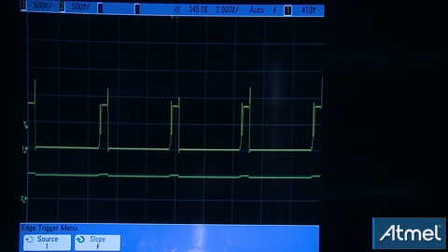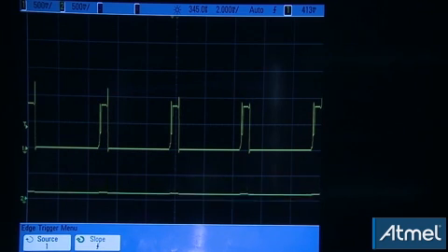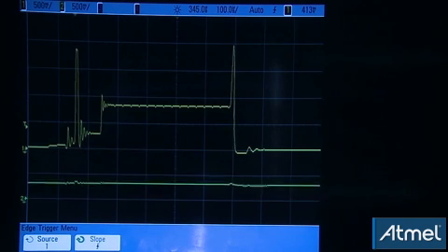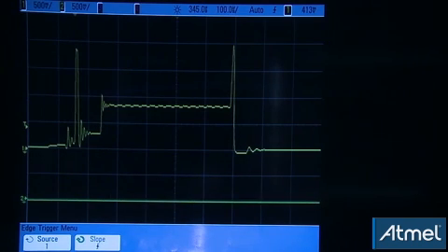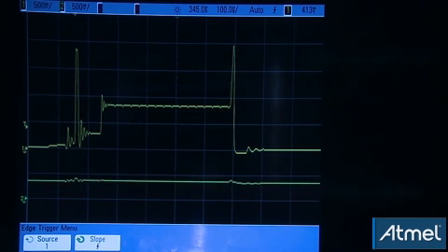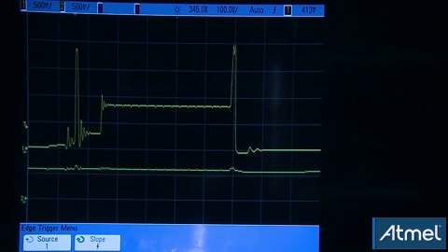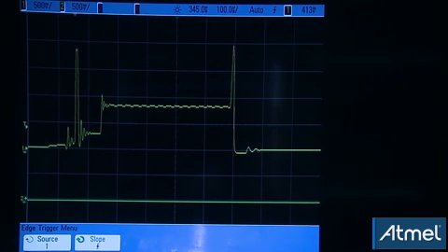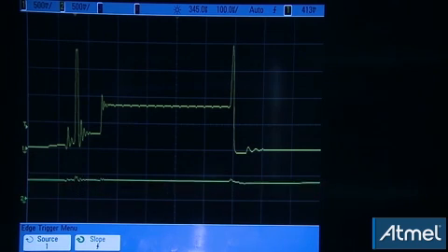You can see where the UC3L wakes up from static and takes a sample that is evaluated by the CPU. The lowest level of the yellow curve is the static mode. The green straight line that we see is our input signal. The instant we have a threshold overrun, the counter is incremented by the CPU and the spike at the end extends a little. So, the CPU has to wake up for every sample to evaluate.